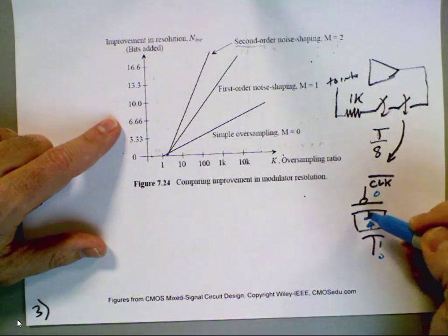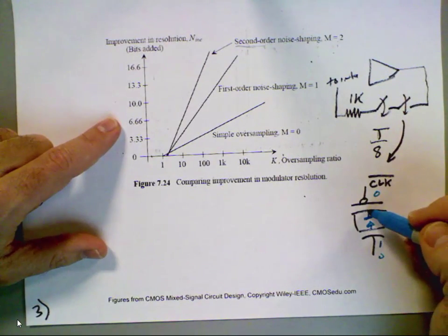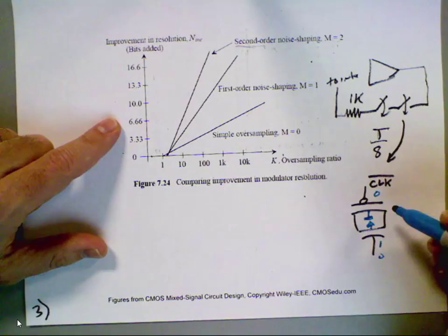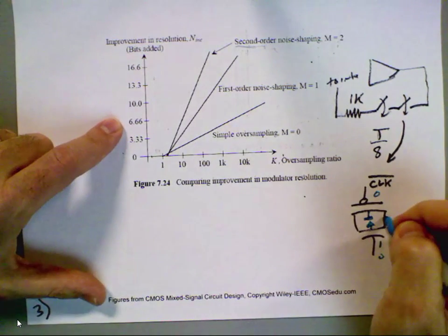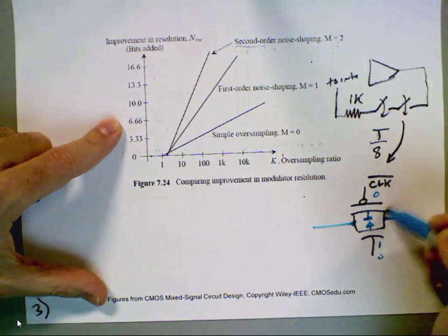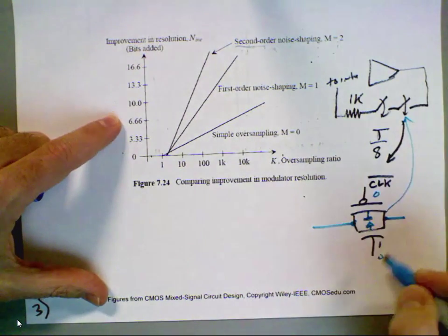If you're not used to this, you can waste a lot of time if you don't have the body of the PMOS at VDD and the body of the NMOS at ground, and it's hard to see with the symbols in LTspice. Okay, so there's a couple other issues, but first, this implements one of these switches.